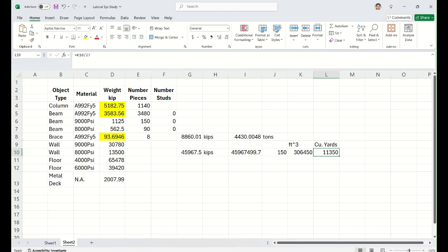Do you understand that? Because this is the total tonnage, but as structural engineers we usually have some index using uniform steel tonnage. To do that, whatever total number, divide by your reference total floor area, right? That gives us the pounds per square foot. So that is something general.